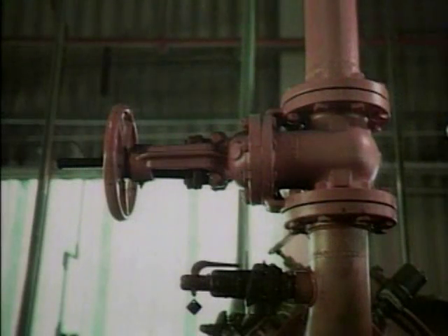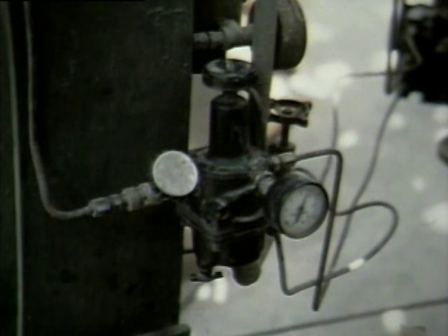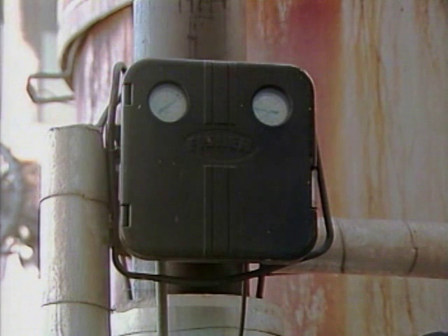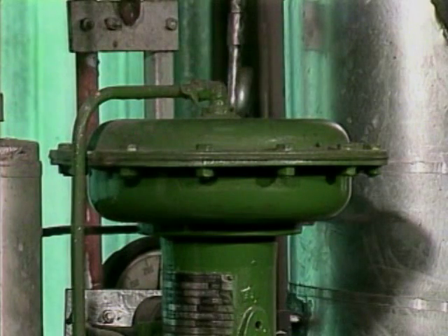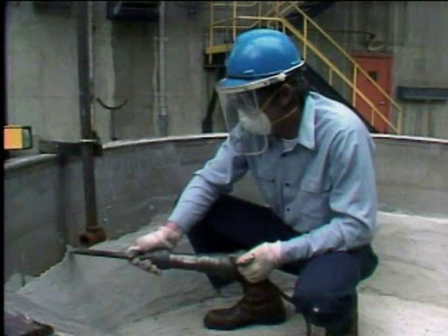Control devices which adjust or change operating conditions in the system typically include valves and regulators that help control the flow and pressure of the compressed air. Instruments that monitor variables in the system are also examples of control devices. The compressed air system also has components that use the compressed air to carry out the system's function. As they do, they create a demand or load on the system. In this system, these components include air-driven or pneumatic actuators and pneumatic tools.